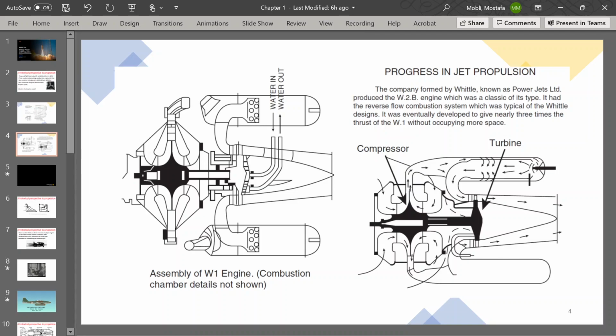In an axial compressor, air comes in, you have the blades, you have the whole compressor system, and then the compressed air goes out at the end, right? But here, you have the centrifugal with the centrifugal blades and everything, so the direction of the flow changes after the compressor, right? That's the idea of the centrifugal compressor. And then we also have the reverse flow combustors. So the compressed air comes here, and then the combustor pushes air back into the turbine blades.